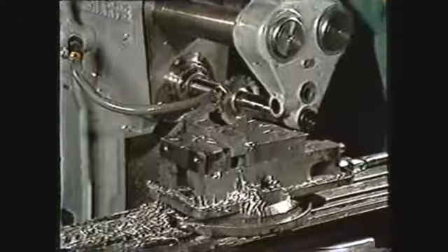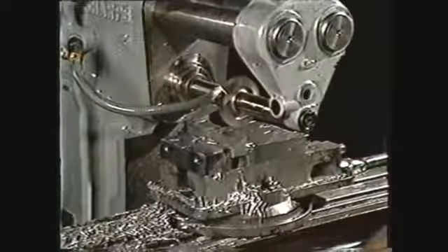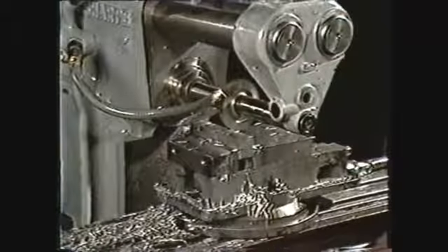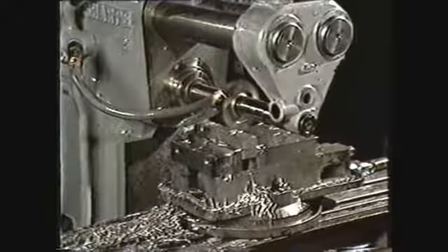To cut a 1/2 inch deep groove in the workpiece will require 2 roughing passes of about 200 thousandths each and a finishing pass of 100 thousandths in the bottom of the groove.